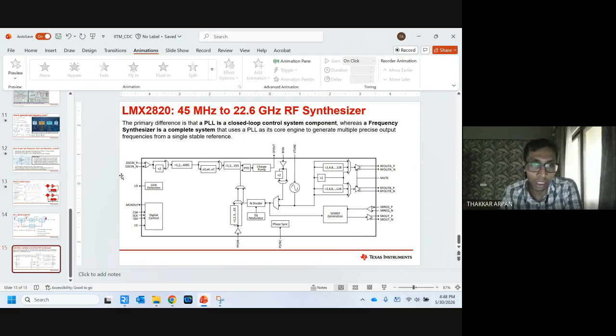So other noises of the amplifier can come outside and all that. So crystal oscillator noise can directly be replicated in the output circuit with a multiplication of N, okay, only till the bandwidth of the PLL. After that, noise of the VCO will dominate and it will not follow the reference. And that noise is going to be usually very bad compared to the clean sources which are available off chip, right?